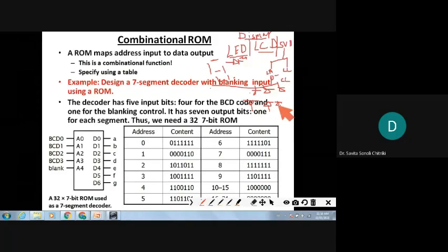This we had seen in the last class. This is common anode. Here this will be connected to each cell. So depending on this, common anode and common cathode will be there. If you send 0 in common cathode, this will be lit. In common anode, each cell is sent 1, whichever you want to enable. So to display 1, these 2 segments we need to enable.